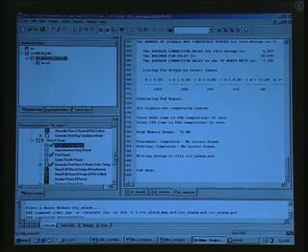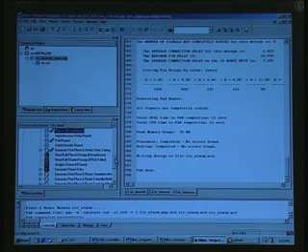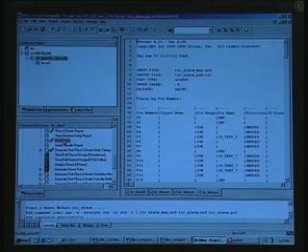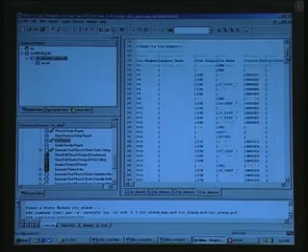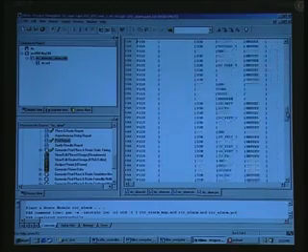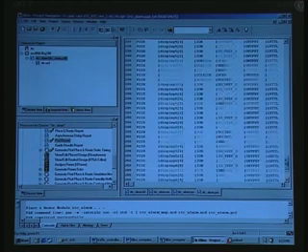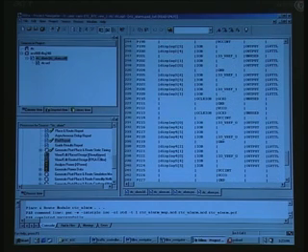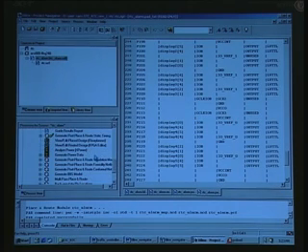And next one is, we have seen implementation, then mapping, then place and route, and you also have a pad report separately, and that will list all the IO pins that have been connected here, and that is what you see here on the right. It may be difficult for you to read, and that is why I am explaining that, and when you actually start using the tool, you will understand this clearly. And anyway, the command summary gives the exact directions, so you will have no difficulty using the tool, and some post place route static timing is also available there.